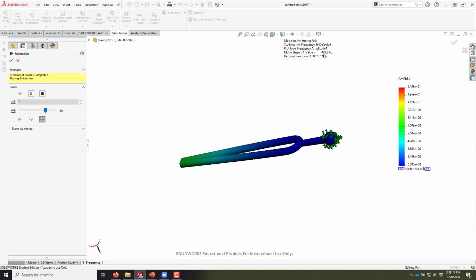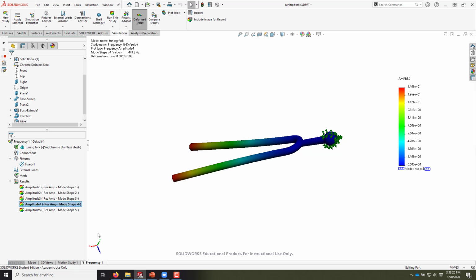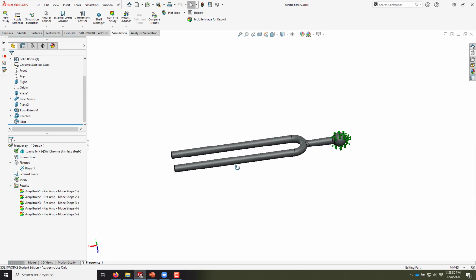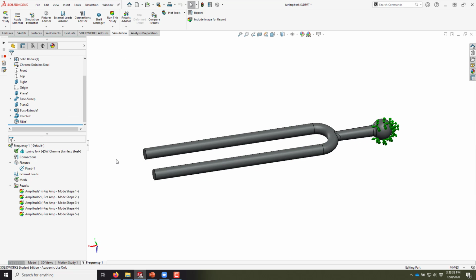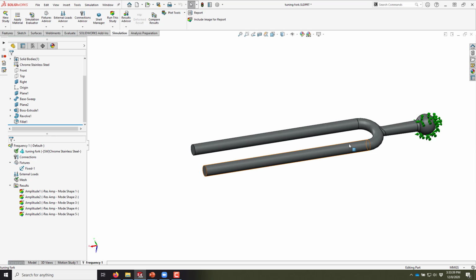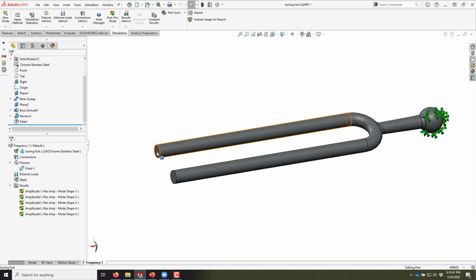Well, a little high. So we can make a quick change. I want this to read closer to 440 maybe, and right now it says 444, roughly. So what can I change about this to bring it more in line? Should I make it shorter or longer? How's that going to change the frequency? And this is the type of thing your students can experiment with. With SolidWorks, they can just make a quick change.